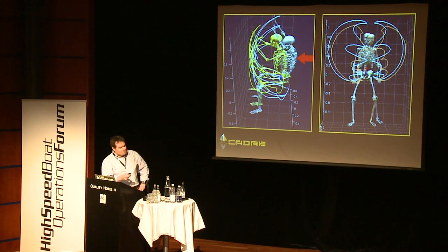When you're not wearing the equipment, you would sit on the seat, and this is your back against the back of the seat here. When you actually put all that equipment on, you're then pushed forward by around 10, 12, 15 centimeters. But interestingly, when you look at how far you can reach, it's around the same. So this is restricted in how far you can extend your arms. But even though you put that on, you don't necessarily have to move the seat forward, because the reach envelope is approximately the same.